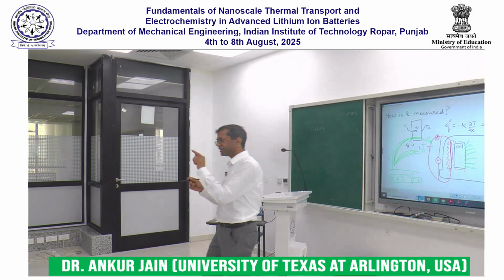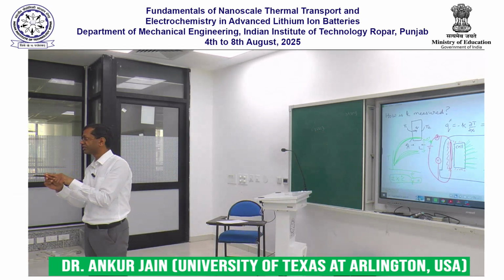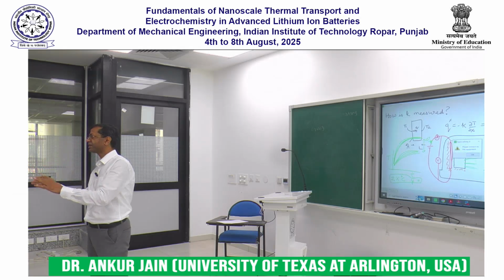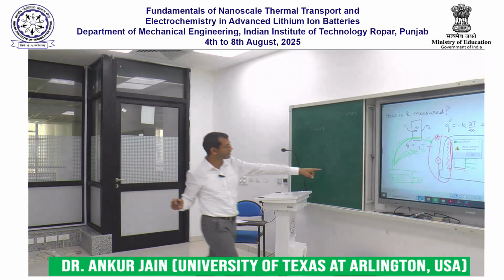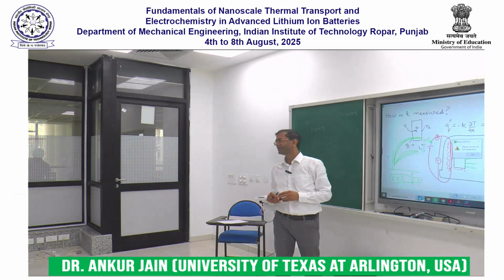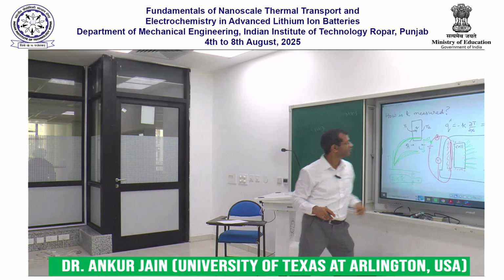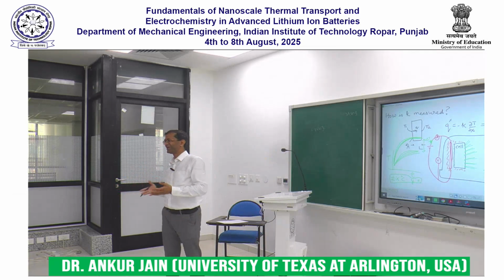So if the temperature of a thermocouple does not change by more than 0.1 degrees Celsius over a 30-second interval, I will say that is my criteria to have reached steady state. So you can perhaps tell your LabVIEW code to look for this criteria. When this criteria is met, that is when I want to take my data. Right? Taking data is very easy, but you have to determine when and how to take your data.